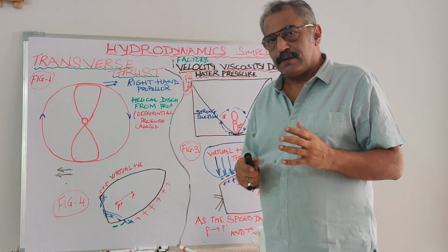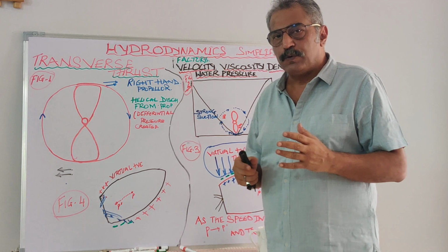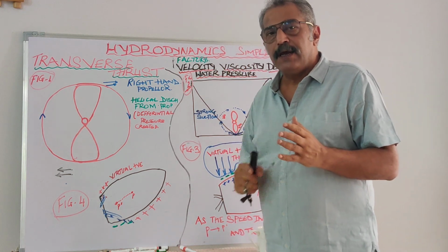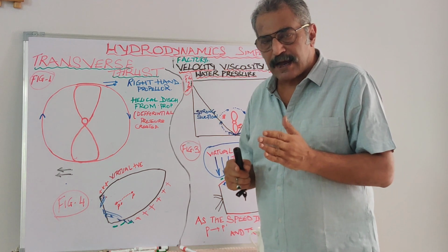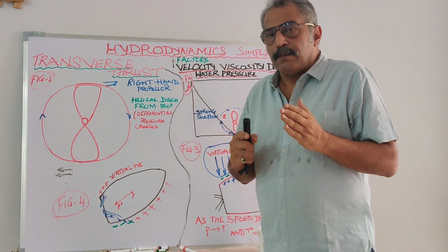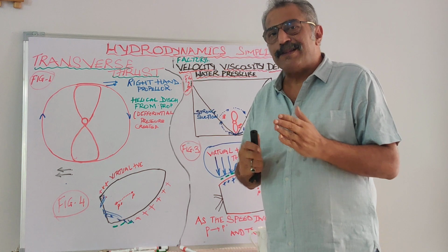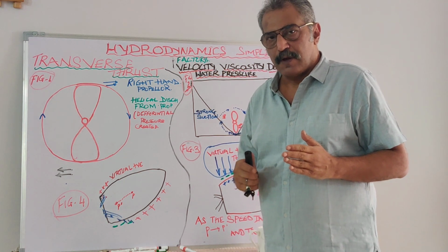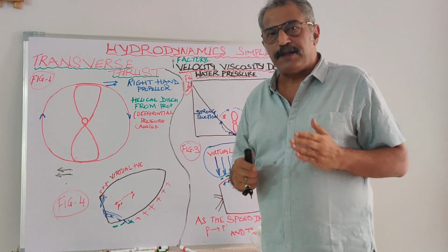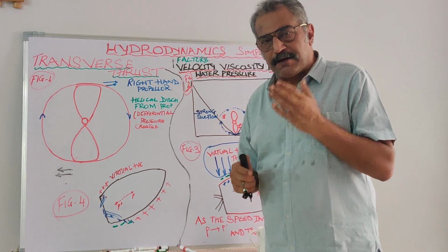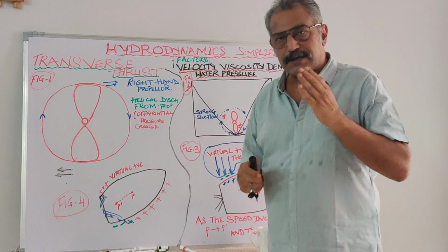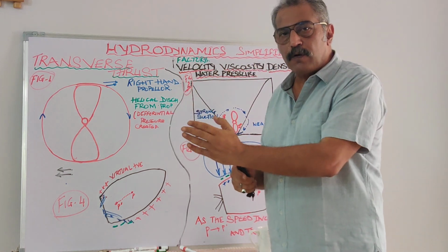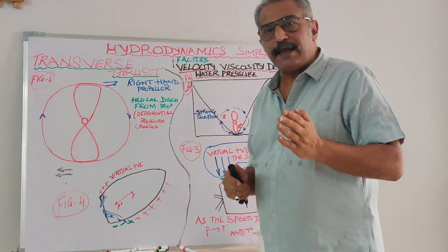So coming to the point, on a right hand screw, when the propeller is churning in the clockwise direction, going on the ahead movement, the bow will start canting to port. But this effect can only be cited when the speed is less. Once the engine speed, the propeller speed, the shaft speed is increased, this effect gets nullified because the head momentum is more than the canting moment.